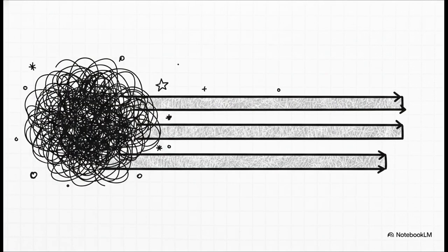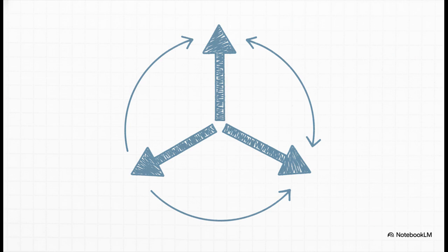Now, to make all this crazy grid behavior actually manageable, we engineers use a classic divide and conquer approach. We essentially break the total impedance down into three distinct types: positive sequence impedance, negative sequence impedance, and zero sequence impedance. You can kind of think of these as three separate mathematical pathways, or lanes on a highway. By separating a messy, overlapping fault current into these three neat little categories, evaluating the network suddenly shifts. It goes from being this impossible guessing game to a really precise, solvable equation. It's pretty cool, right?